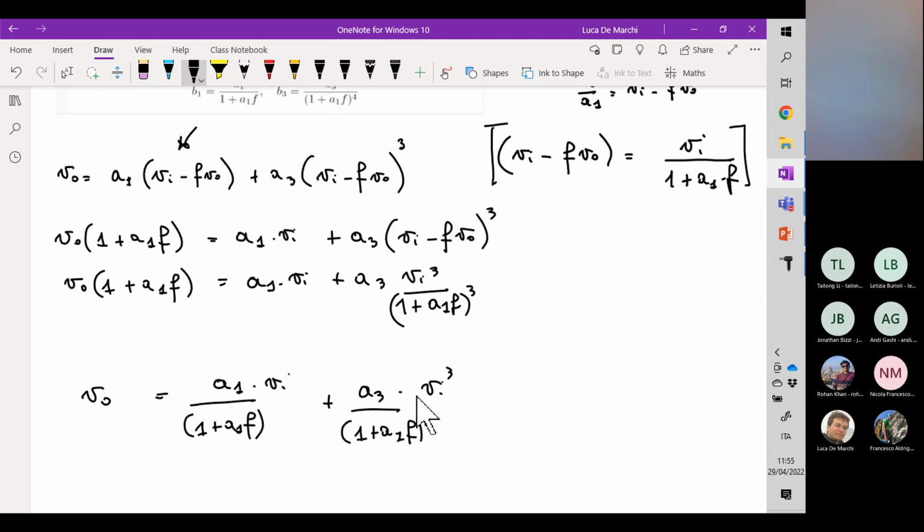Similarly, in the phase plot, each pole generates a phase loss equal to minus 90 degrees, and this is combined for all the poles. So first pole we lose 90 degrees. After the second pole effect, we lose 180 degrees, and so on.